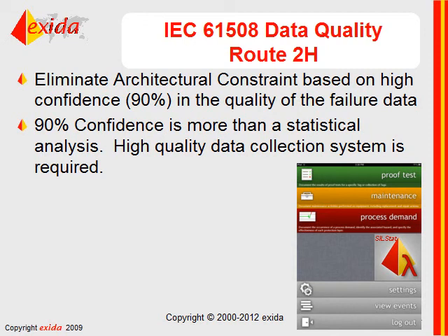It's a matter of judgment regarding the quality of the data collection system. So don't think it's just a statistical issue. You really have to have a good, high-quality data collection system. But the reward is, if you do, you will have good data that will typically allow the PFD calculation to be the limiting factor when you do your SIL verification.